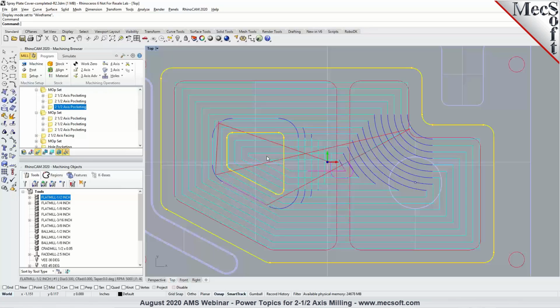I want to jump in here, Uday, and talk a little bit about tolerance stacking. You mentioned that, but I want to dive in a little bit deeper there. One of the things when we do arc fitting, we are actually fitting arcs to the toolpath points. So we are looking at just a toolpath and fitting the arc geometry to it. And obviously, when we do that, we have to use a particular tolerance to do it. So this tolerance is independent of your machining tolerance. So in some cases, it might actually introduce some errors because we are using an additional tolerance on top of